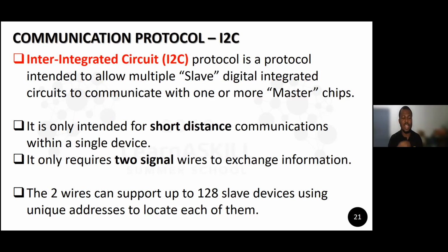The frequency at which the communication is proceeding has to be factored in, because the longer your cable, the more cable capacitance sets in, and signals tend to be attenuated. So when we talk about these protocols, we are looking at very short distances, not the Ethernet cable form of communication where you can proceed over very long distances.